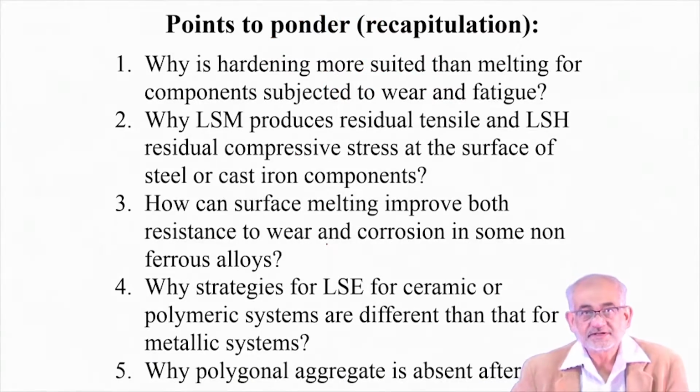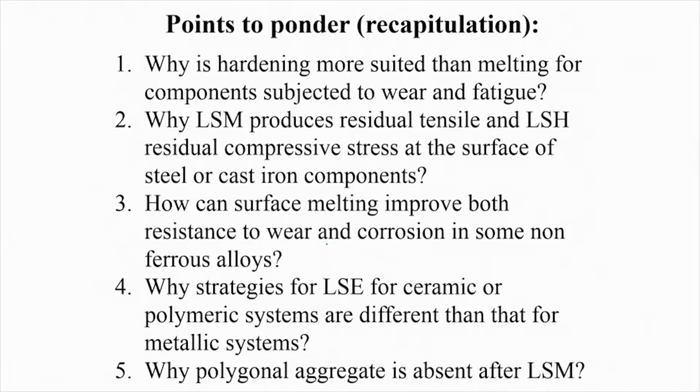So let's try and summarize what we have discussed: hardening without melting as a strategy is more applicable to steel because it produces not only a predominantly martensitic microstructure, but also residual compressive stress, which is beneficial to improve both resistance to wear and fatigue.